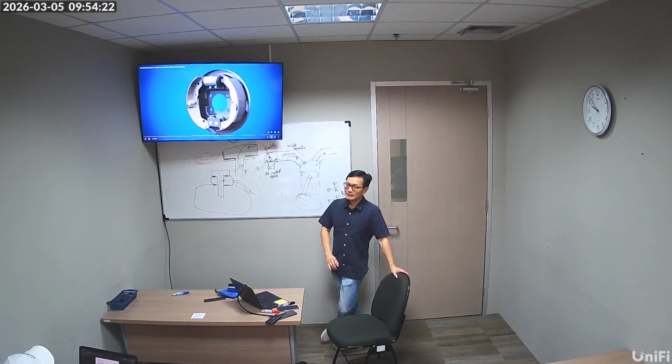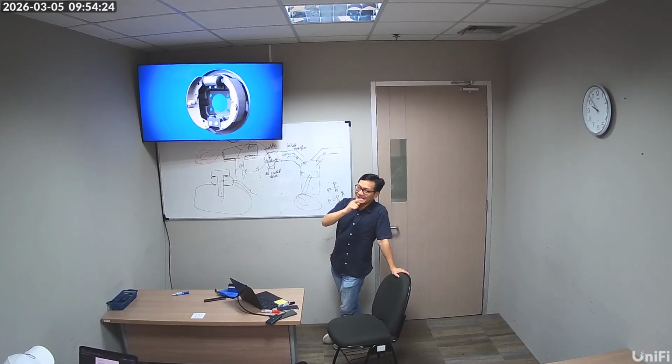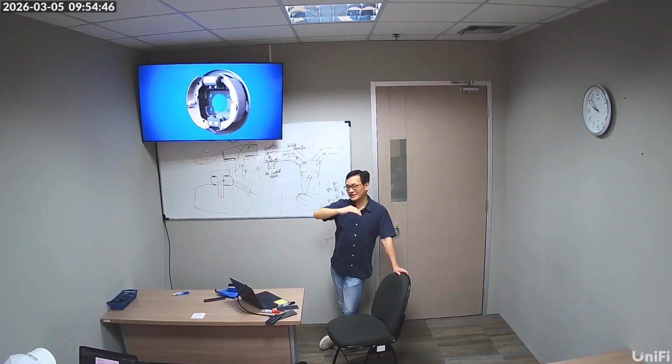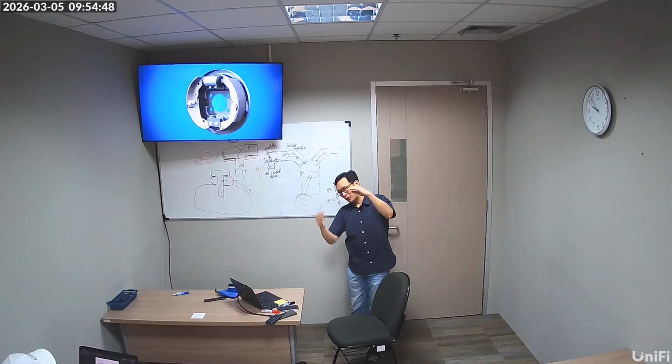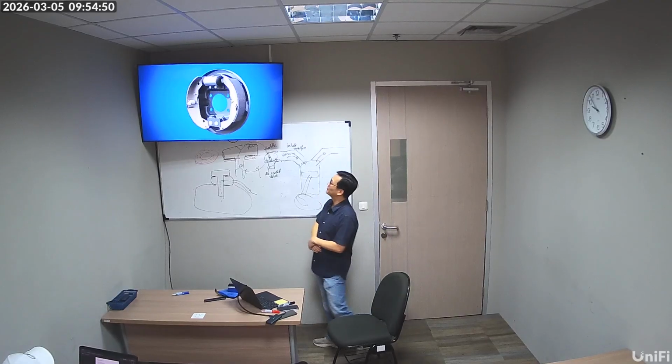No, actually the shoe is thicker on the bottom, so you have right and left. They compensate on that thickness. You have right and left, so you want to put right, left. You can't be switching any of it, or it's going to be uneven wear. The lower part is thicker than the upper part. So it compensates, so when it swings, you make full contact. Yeah. Good point. Never noticed that.